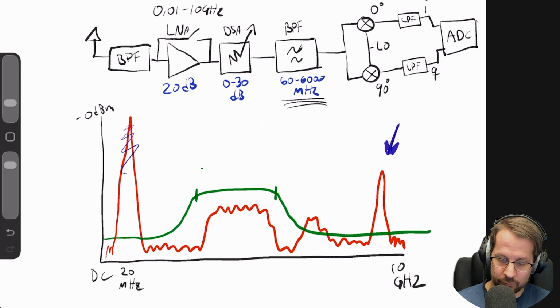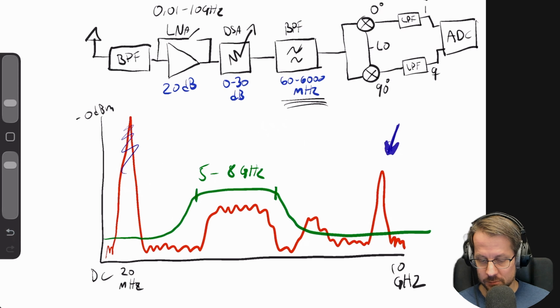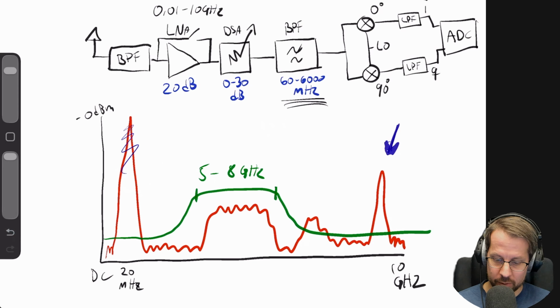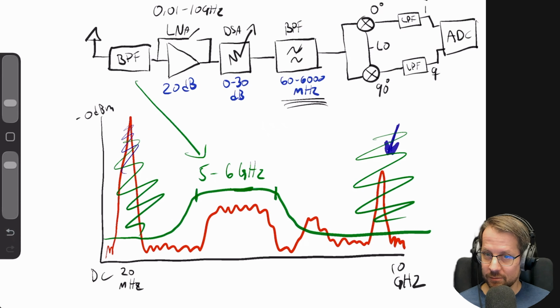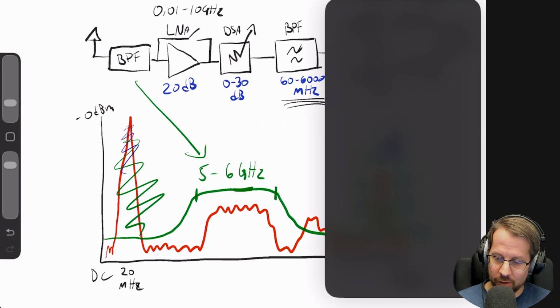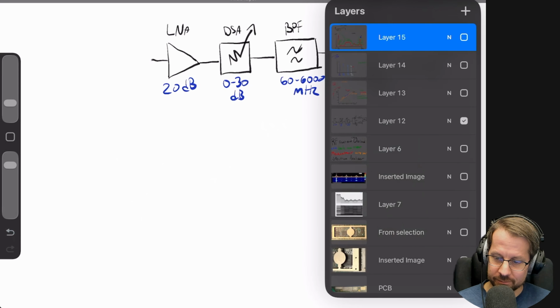So let's say this is from 5 to 6 gigahertz, for example, because that makes more sense. So a 5 to 6 gigahertz bandpass filter covers all the 5 gigahertz Wi-Fi, right? So this will attenuate everything of this and everything of this, right? So whatever you are out there to measure, use the proper filtering, and be careful not to overload any type of spectrum analyzer, right?